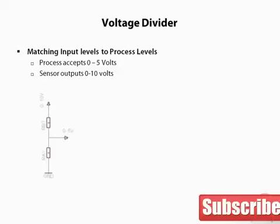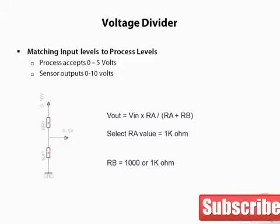Here is our circuit diagram, again, except Vin equals 0 to 10 volts and Vout is equal to 0 to 5 volts. Looking at our equation again, Vout equals Vin times RA over R total. Since our equation is ratiometric, mathematically it doesn't matter what the exact values of the resistors are, only the ratio of them. So for now, let's arbitrarily choose RA equal to 1 k ohm. Then solving for RB, it is also equal to 1 k ohm.